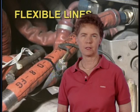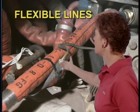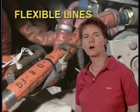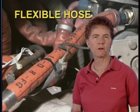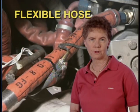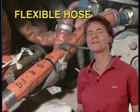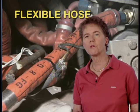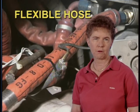Let's talk now about fluid lines and fittings. And let's start off talking about flexible lines. These are our flexible lines for carrying different types of fluids. Now, flexible hose can be used in aircraft fluid systems, but only according to the manufacturer's specifications. So you've got to make sure where flexible hose is allowed to be used on different aircraft.